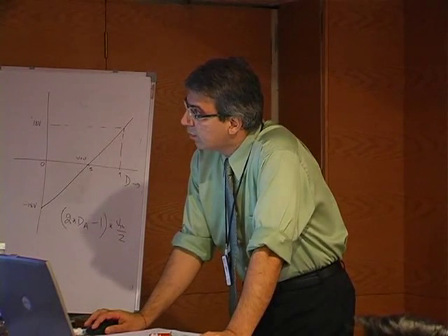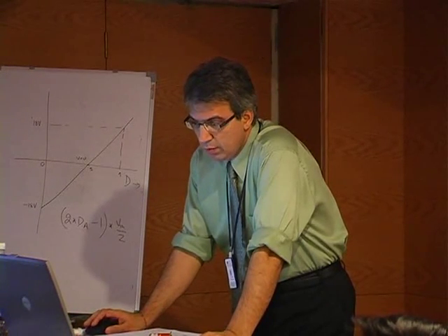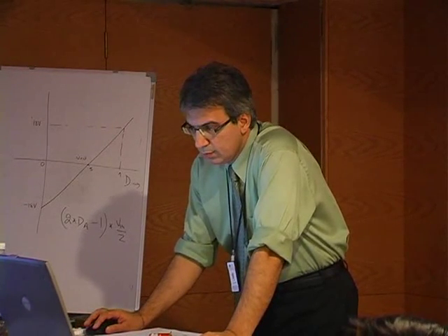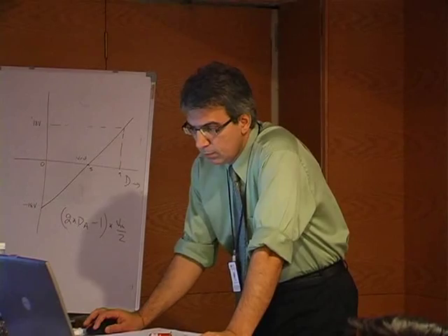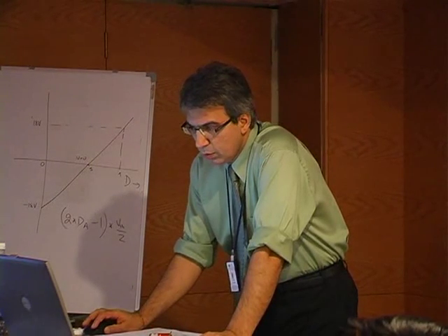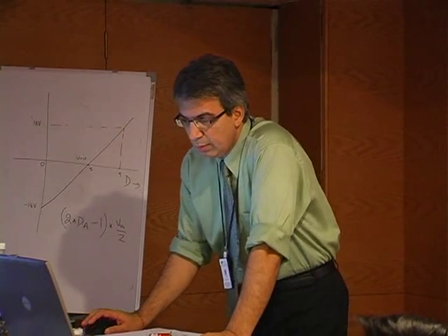So this is the inverter, and we have essentially 400 volts on the DC bus. So you can run for 100 milliseconds, and maximum step size is 10 microseconds.